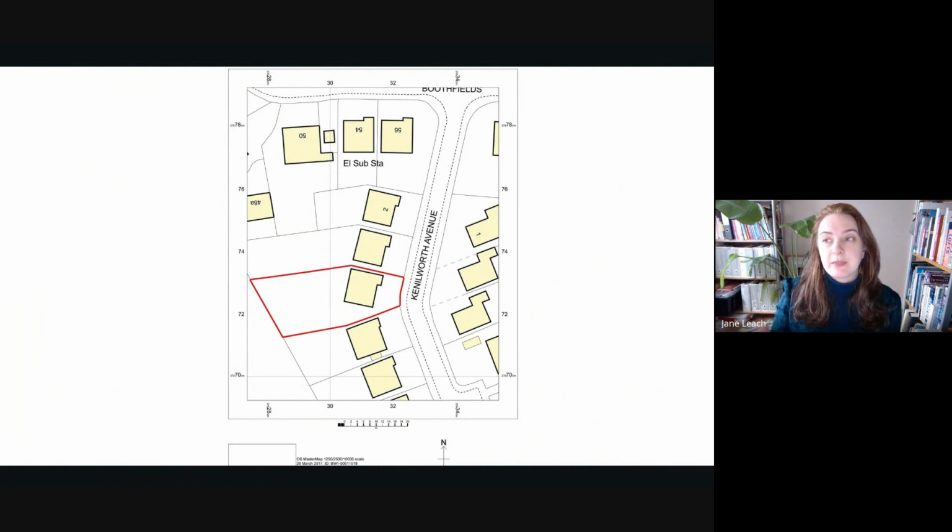It didn't used to be there, so you used to have to create your location plan separately, and I always created them at like 1 to 500 scale, so that it could act as a combined existing site plan and location plan at the same time. I've had pushback from planning departments now, so that's not necessarily possible.